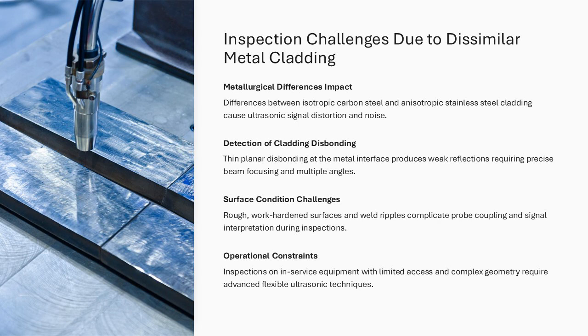Surface condition is another factor. Cladding surfaces may be rough, work-hardened, or exhibit weld ripples that complicate probe coupling and signal interpretation. From an operational standpoint, inspections are often performed on in-service equipment with limited access, complex geometries, or elevated temperatures.